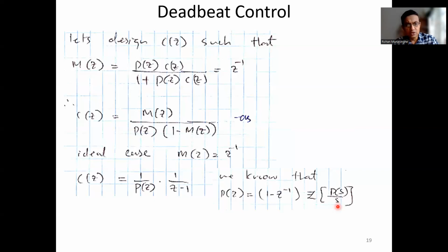So when you have a difference equation, you know how to calculate the samples every time k. This is exactly what you want when you want to control a plant, right? You have a computer or a microcontroller or single board computer, whatever it is, which will run this polynomial, or difference equation rather, and calculate the control signal every step. And then you put it into the actuator.